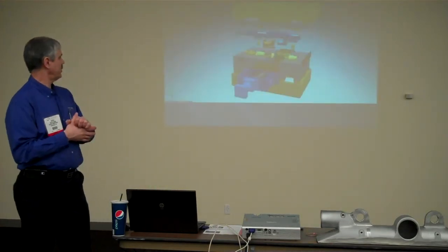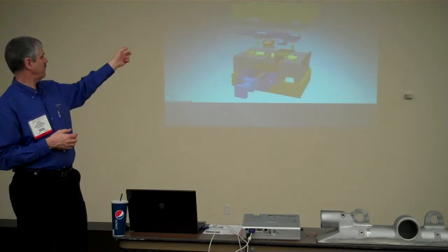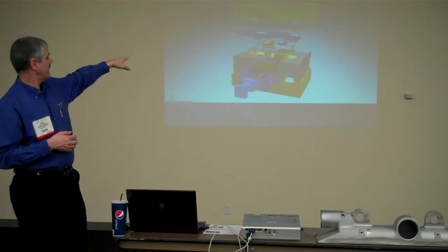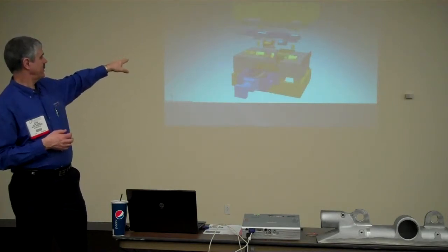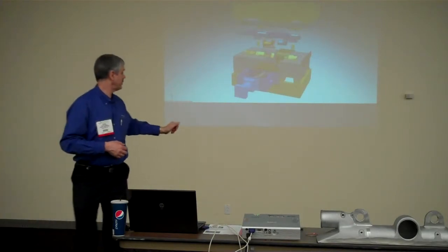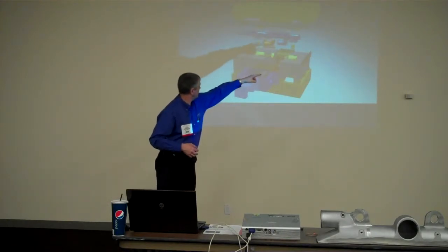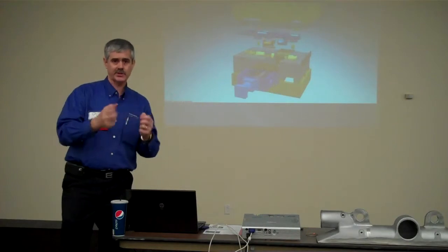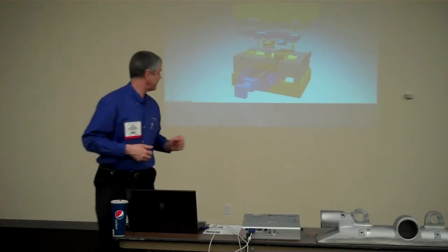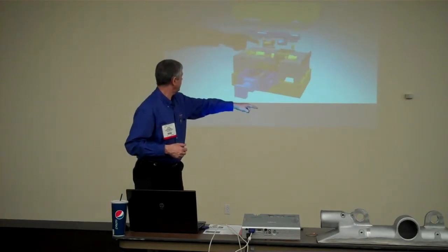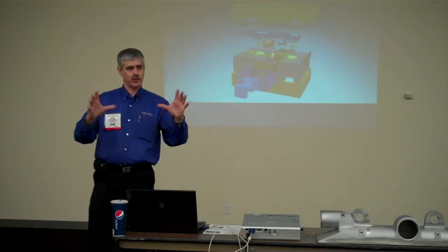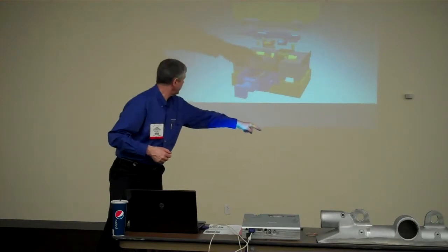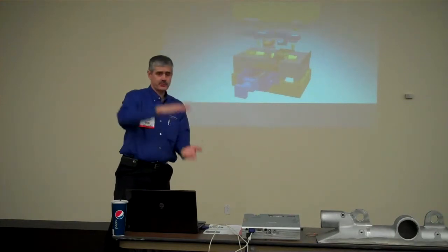An exploded view of a mold: the top mold half would be what we call the male mold half. The casting with the gating is shown in the middle. The exploded view shows that there's a sand core here that gets placed right there. That's an expendable core that we set in the mold, pour aluminum around, and then shake out. In this particular case, there's cast-in bushings right here. Those are steel bushings that are placed in the mold. Aluminum runs around them. And this mold also has sliding cores that come together to produce a feature that doesn't draw out in the mold.